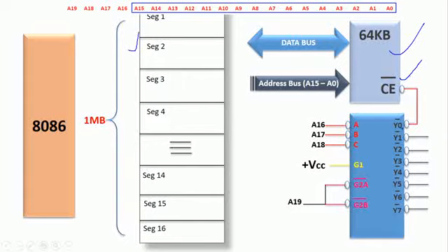In order to choose one of the output lines, you are supposed to give the proper input combination to this address decoder. That input combination should come from the address lines of your memory address bus coming from the microprocessor. So three address lines of the address bit positions coming from the microprocessor are used as input lines.